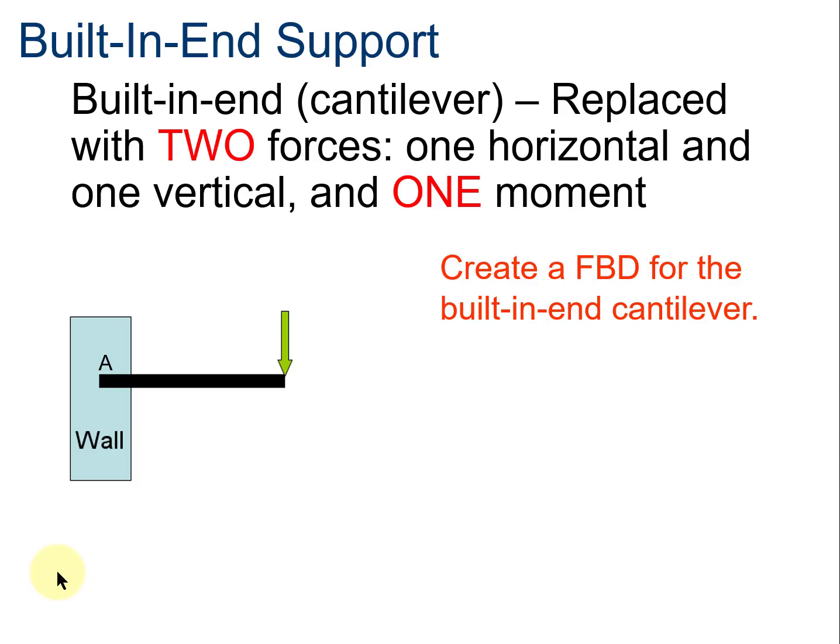Okay, built-in support. A built-in support, or cantilever, is replaced with two forces, one horizontal and one vertical, and one moment. Okay, here we go. So let's create a free body diagram for this one. It's like a diving board sticking out of a wall at point A. So let's draw our beam here, and we've got this force out here.